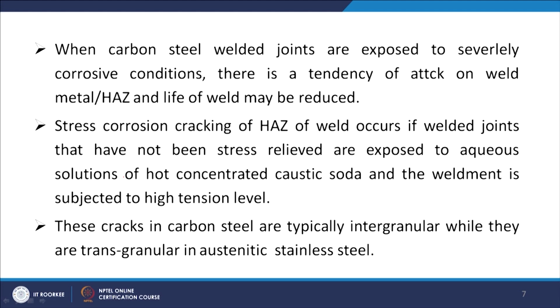So, one is that it is exposed to that atmosphere, and also it is under that tensile environment to a very high level. If you talk about the carbon steels, the cracks you observe are normally intergranular, and if you look into the austenitic steels, they are normally found as transgranular type of cracks.